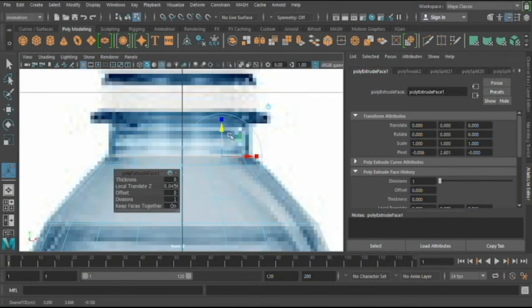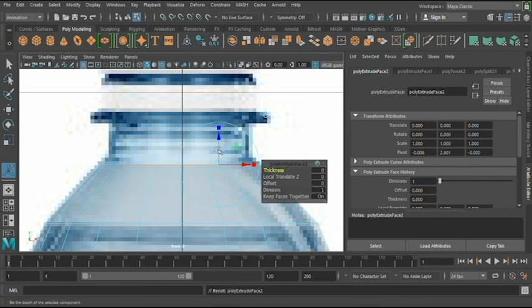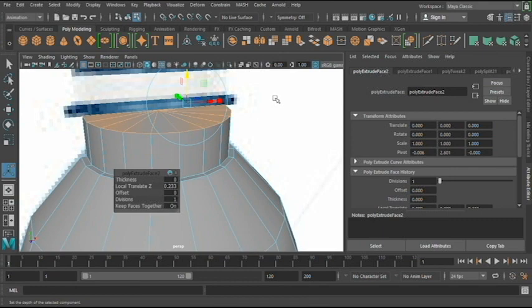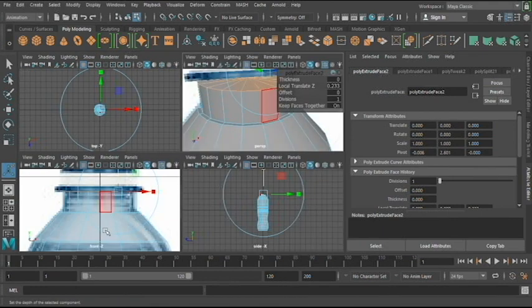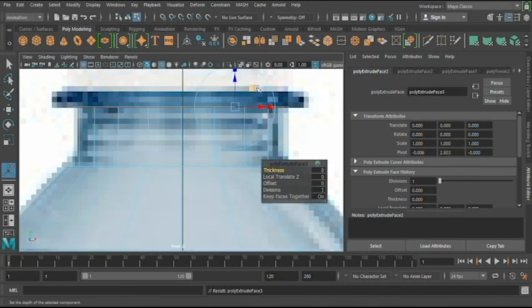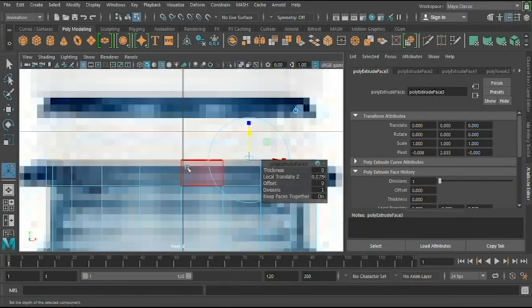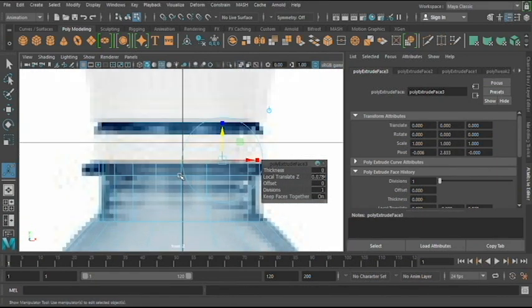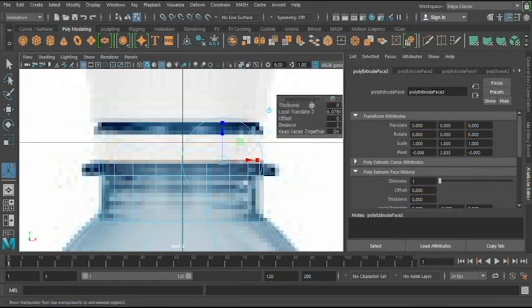And then from here, we're going to click the extrusion tool again. So we extrude only from that face so we can see this. Now we've created this part. Now we're going to extrude again, only to the tip of that part. I'm going to focus by pressing F, okay, and then I think I'll just move this up. I'm going to extrude one more time.